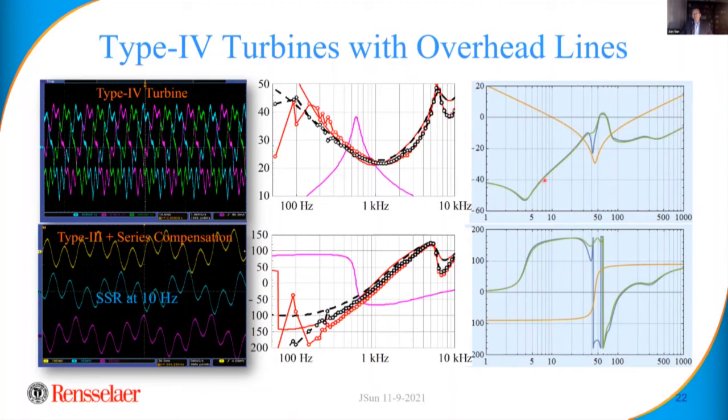On the other side, you have an inductive impedance. And when the magnitudes become equal, that basically indicates a series resonance. And a phase difference larger than 180 degrees indicates that the net damping at that frequency is negative, right? So it's an unstable resonance. Based on that, you can predict unstable resonance in the system at that frequency.